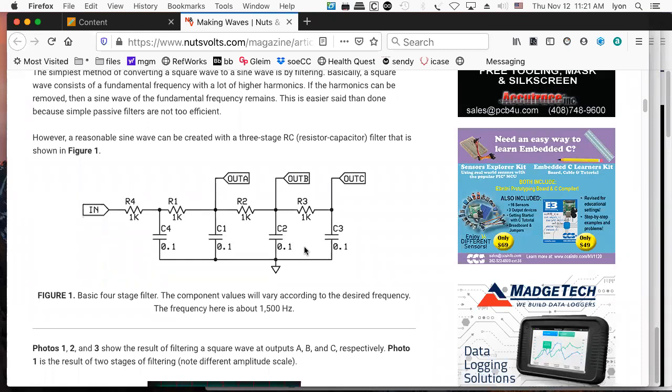So typically what happens is we say something like, oh, well, people can hear from 0 to 20 kilohertz. We're going to sample at 44.1 kilohertz. That's typical CD audio, which means we can have frequencies that go from 0 to 22 kilohertz according to Nyquist, but we can only hear from 0 to 20 kilohertz. So what we do is we start our cutoff at 20 kilohertz and we finish it at 22 kilohertz, because we need to roll off the higher frequencies gradually. That makes sense, because if you do it too quick, you get all kinds of distortions, and it doesn't sound good. It'll just distort as you get up into the higher frequencies. So giving yourself that extra 2 kilohertz of headroom in bandwidth is really critical when you go to design the system, because Nyquist is a theoretic thing. It's not a practical thing.